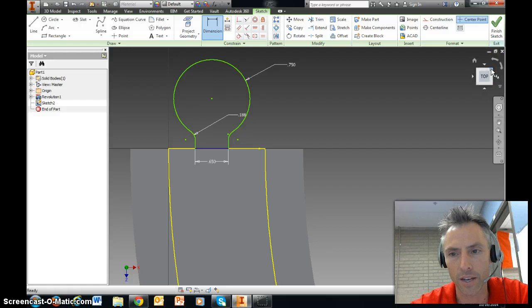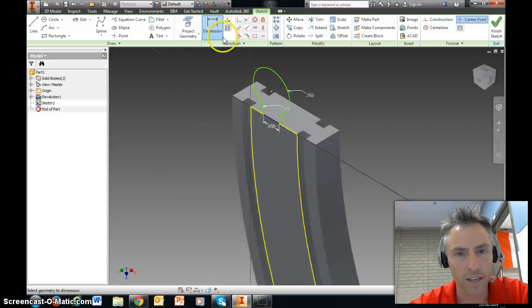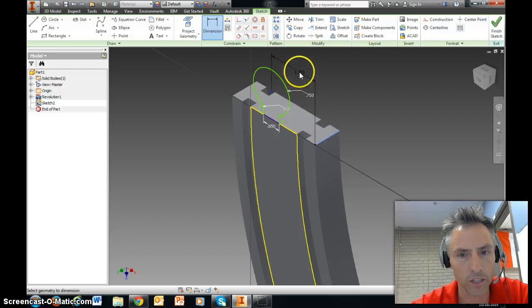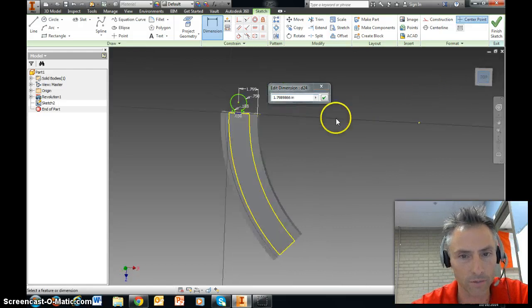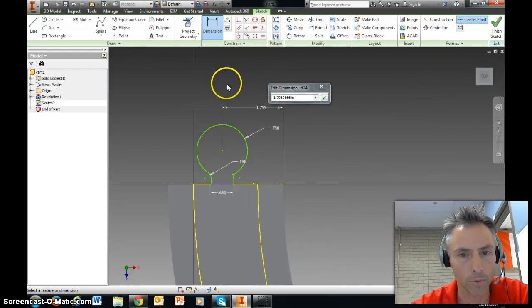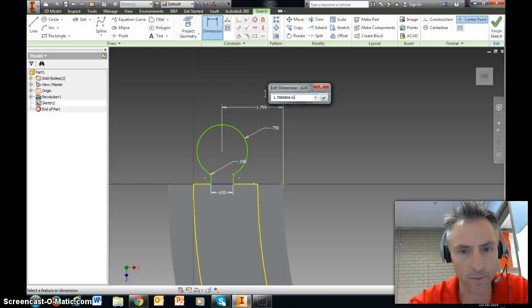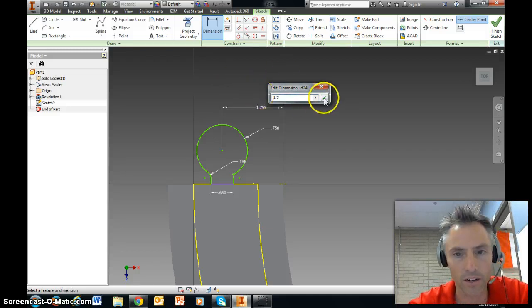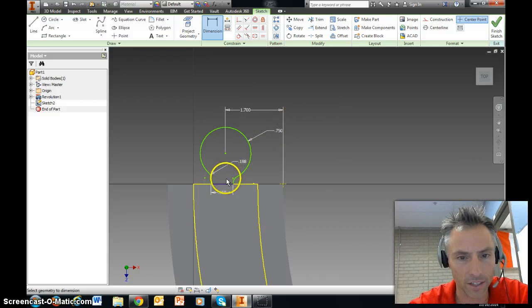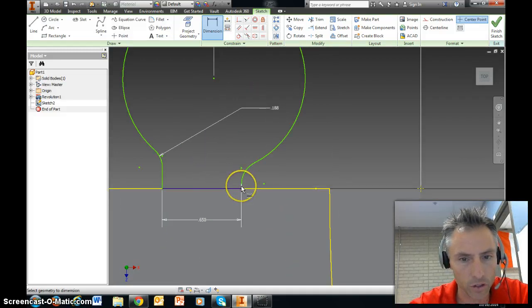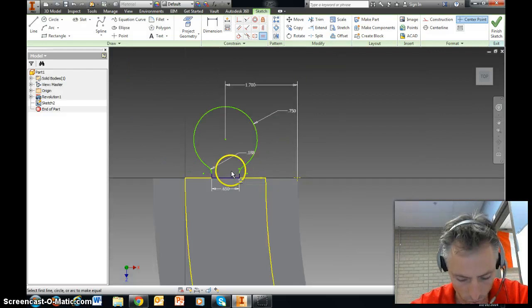Now I'm going to tilt this thing so I have a view of one of the edges. And I'm going to do a dimension from the center point to this outside edge. And I want to make sure that that is going to be 1.7 because the entire thing, if you remember, was 3.4 inches wide. So if I tell that dimension to be 1.7, then I know it's going to be centered. Now did you see how that just tilted? Okay, so I've got this little straight piece right down here and this big straight piece right up here, and I want them to be the same. So I'm going to go up to this equal constraint right here. And I'm going to tell that little guy and this bigger guy to be the same. And that keeps it symmetrical.